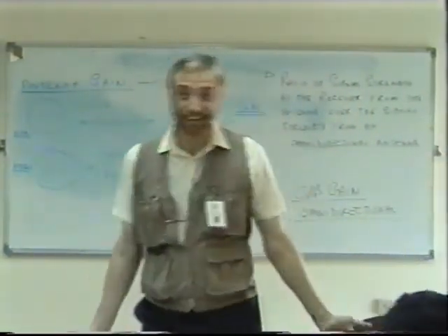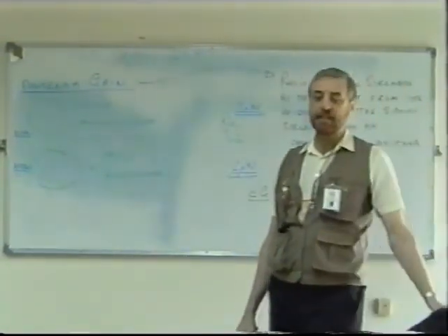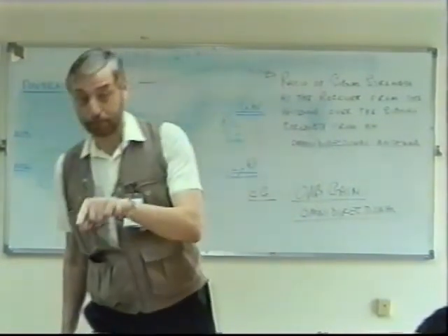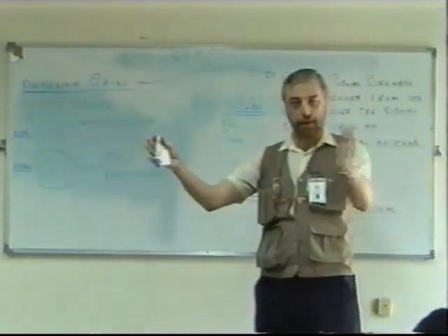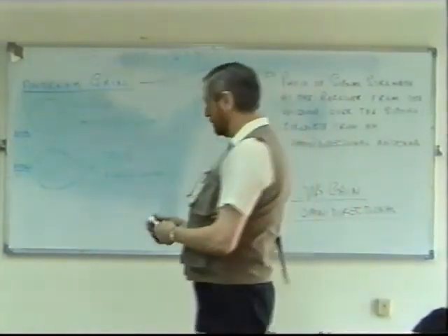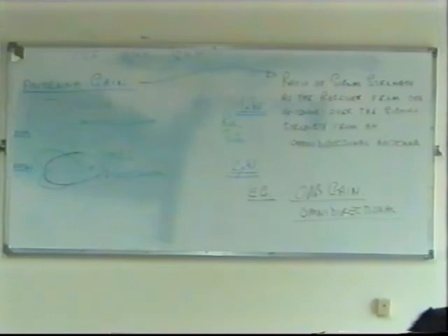No, you do not buy it, because it must have a 0 dB gain to be omnidirectional. It can have slightly more than that if it's a stacked array. But if you're talking about a 25 dB gain, you're talking about a reasonably narrow polar diagram, something like this. So it's not going to be suitable in any way for mobile communications. Doesn't matter how cheap he tries to sell it to you.